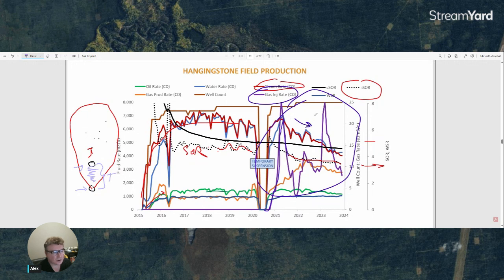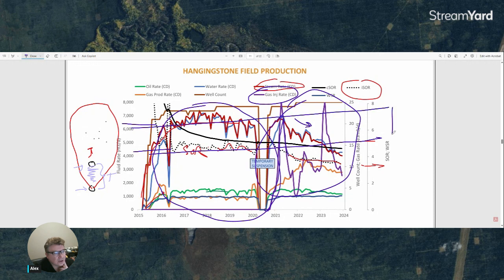So you reduce the steam requirement, with the NCG injection going in, and now you go into this new technology scope where you haven't been in the first 5-6 years of the life of this asset. Again, the asset itself is 5 pads, 5 well pairs per pad. And now you're reducing the steam requirements, going from, I would say, 6,500 cubes to maybe 4,200 cubes, as seen here. And you're capturing the delta of value, which is really, really cool.